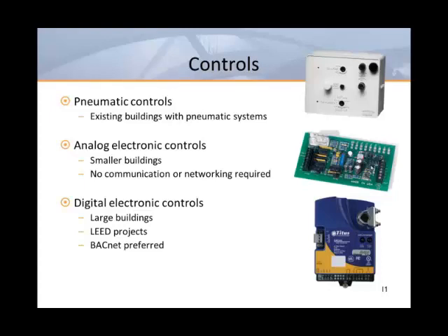In order to achieve LEED points for building control and energy optimization, digital controls are almost always going to be needed. Digital controls use the latest PID control algorithms to provide excellent airflow and temperature control. They're usually networked and become part of the building management system. For many years, the industry has been moving towards interoperability between control devices. BACnet compliant systems are rapidly taking over the building controls industry.